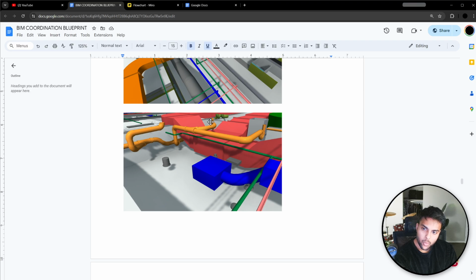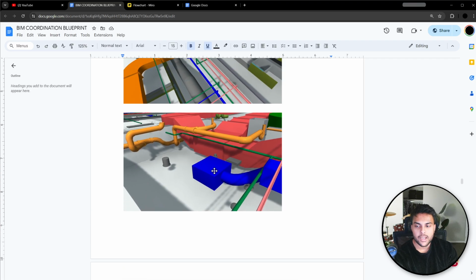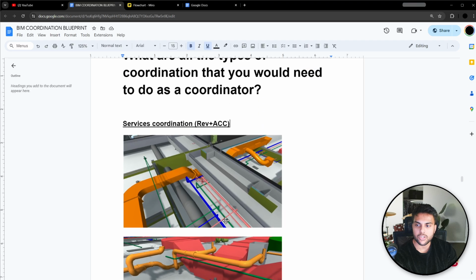with this, right? So wherever you do that U, and you can't move this pipe because it's going up into the toilet because the architect has designed the toilet to be there, right? So then you drop down, and then you have this whole area over here, and then that ceiling space has to drop just below this. And so we had to lower the ceiling in this area because the hydraulics dictated where the mechanical went, and then the mechanical dictated where the ceiling had to be lowered to. So things like that, right?